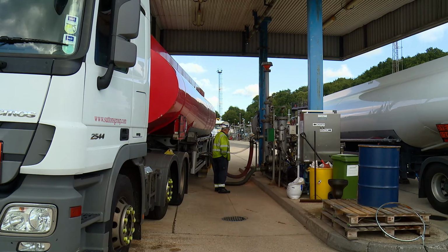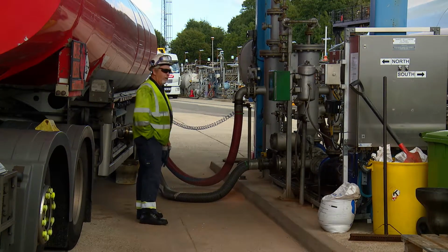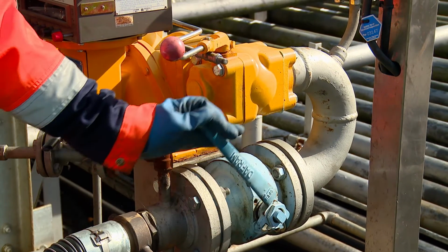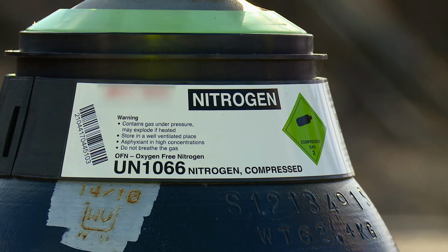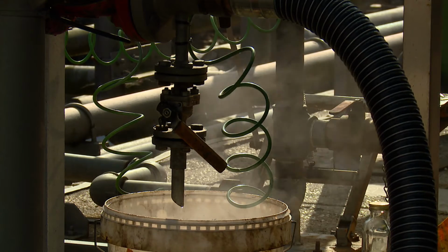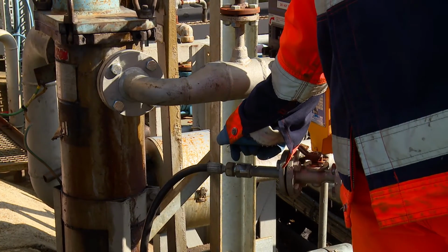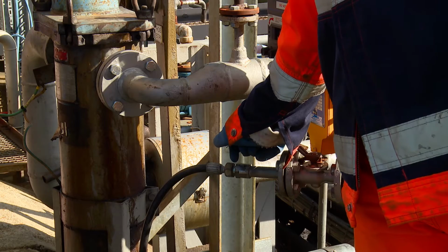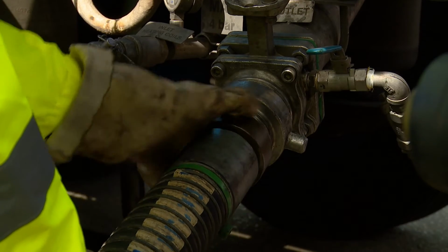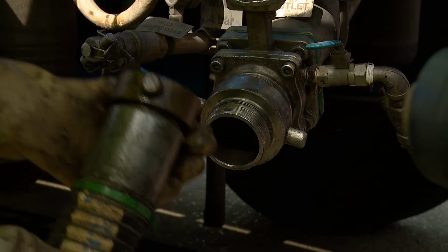When discharging, the end of loading will be indicated by a change in the noise of the discharge pump, which is then switched off and valves and vent are closed. When the transfer is complete, connection hoses may be cleared using a nitrogen purge if available, which returns the contents of the hoses back to the vehicle or tank and avoids spillages. Alternatively, hoses can be drained into a suitable collection receptacle and then disconnected.